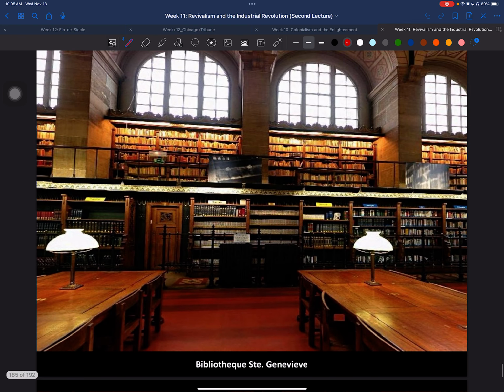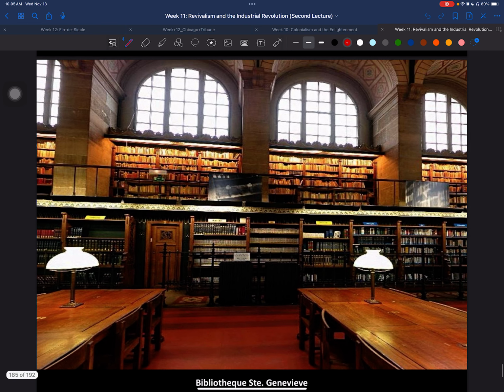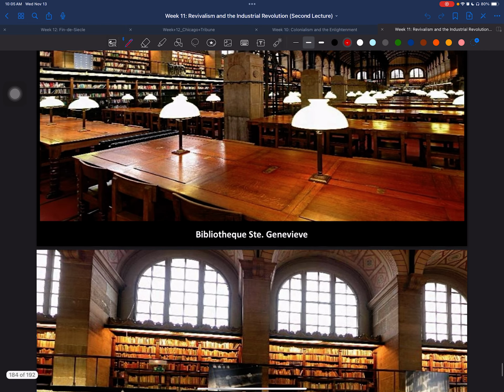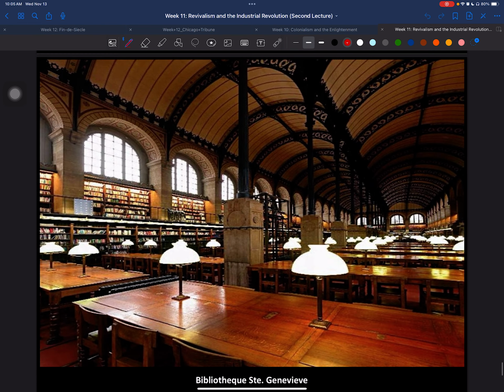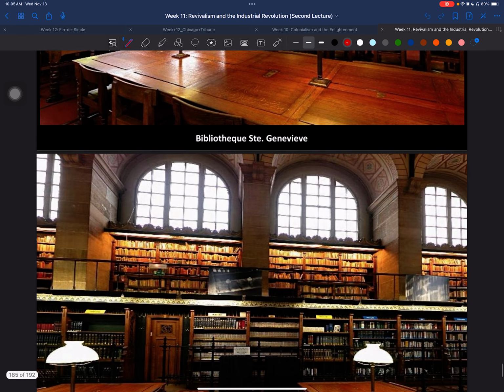Here are those skylights coming in. And part of what's so great about this system is notice how light that roof is. So the loads on these exterior walls are negligible compared to what would have been a traditional roof type of construction. This is super light. What that allows you to do is open this up and have much more daylight in there, versus if you had a stone roof up there, you would have had to make really heavy supports, and that would eliminate the amount of glass you could have.